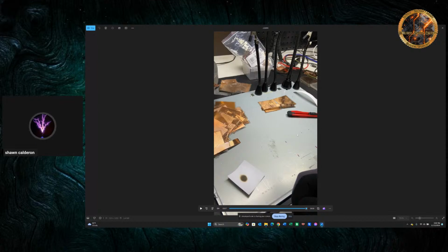And so now I'm on version 3. I'm going to walk you through how I did that. And I'm going to get the capacitance up to 150 nanofarads. And so in effect, I will have built a high frequency, high power, high voltage capacitor to use in all my Tesla coils. And it will all be from things you can buy at the craft store or order on eBay, very inexpensive. And I'm looking forward to seeing the unique effects of a mica capacitor versus the standard plastic capacitors that we use.